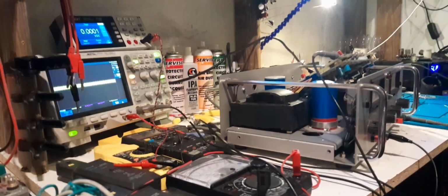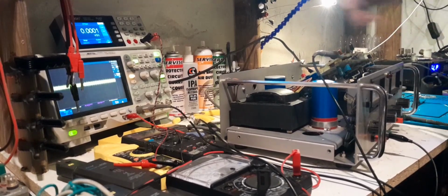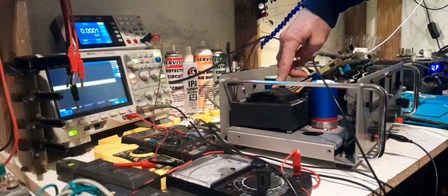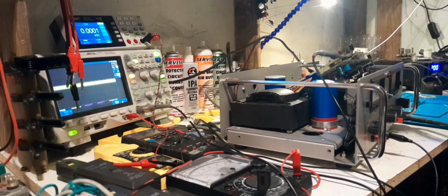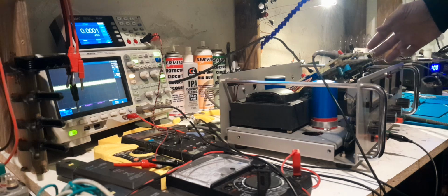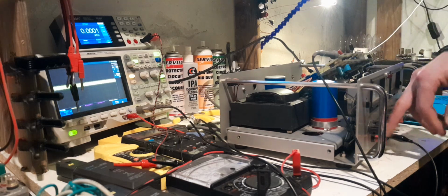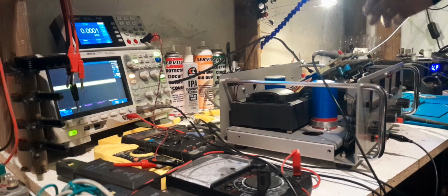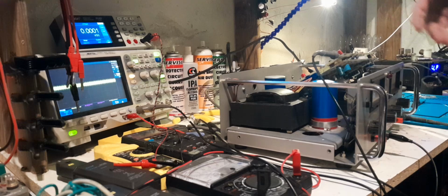I spent so much time. See, the thing is, this thing's got that many different windings on it. Obviously all the different circuits are referenced to each other in one way or another, whether a reference circuit is referenced to the positive terminal or the negative terminal, and then that goes back to an op amp, and the output of that goes into another op amp. Obviously everything's all connected, but when I probe things around, I like to try and look in between the 0 volt point of the power rail or the center point of a power rail and the device's inputs or outputs or whatever.